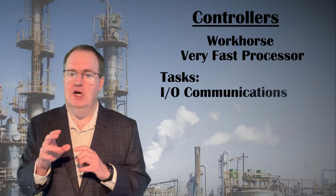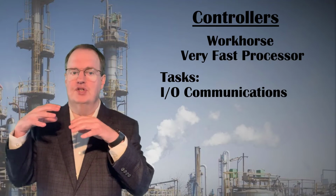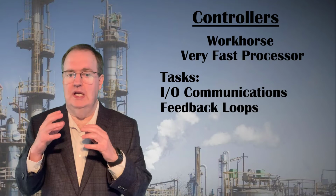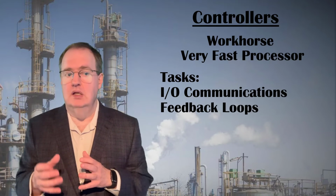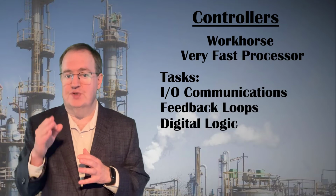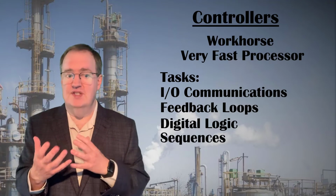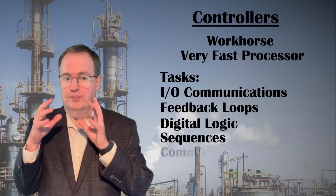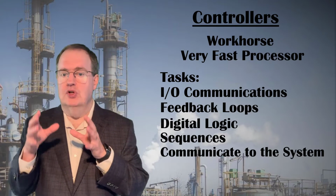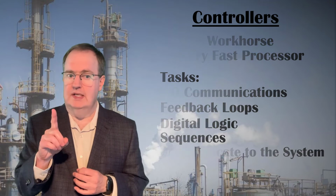Controllers first have to process all of those I/O signals, scaling and aliasing to tag names as needed. Feedback loops need to be iterated several times a second. Lists of digital logic, that is, interlocks and permissives, must also be processed, as well as sequential logic in phases for batch plants or production modes for continuous ones. Controllers are very fast computers processing many lists of tasks one at a time.